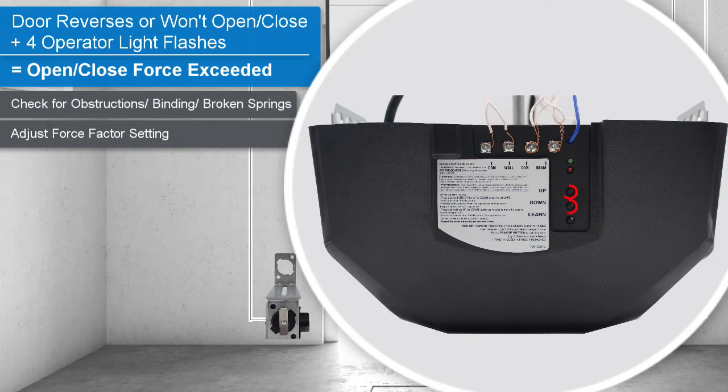Press both the up and down buttons simultaneously for 3 seconds. The operator light and red and green indicators will flash twice. Next, use the up and down buttons to change the force factor setting. The force factor has 3 settings, indicated by the green and red LED indicators.